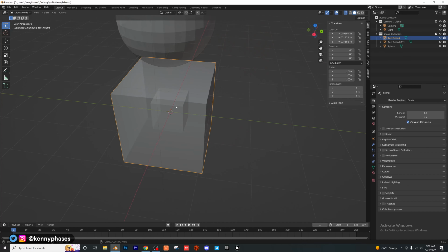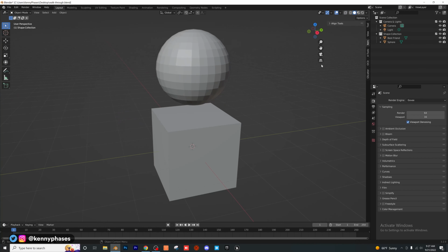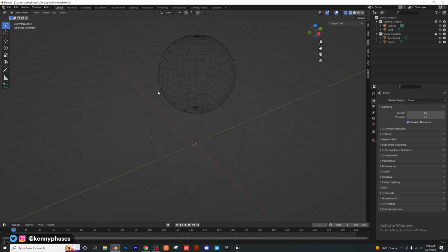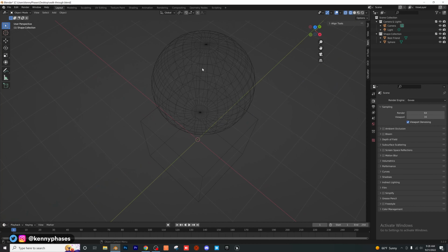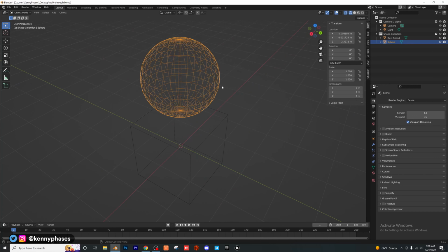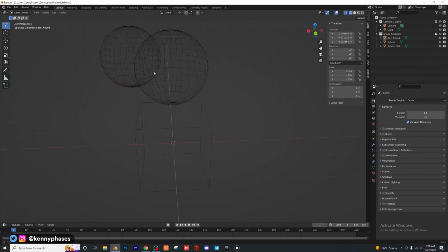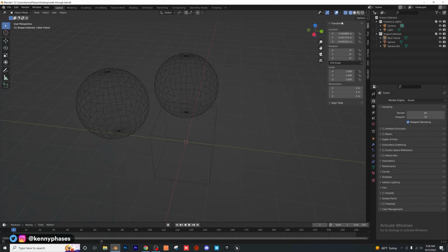I'm going to go ahead and actually delete that inner cube, and I'm going to toggle X-ray back off. Right now we're in solid view, and that is this little sphere right here. This, to the left of it, is wireframe view. And what that allows you to see is the wireframe of the objects, all the vertices, the segments, the vertexes, everything that makes up the object. You'll be able to see it in this view. It is similar to X-ray because you can see through the object, but it just allows you to see the actual geometry of the object and what it looks like. This is super helpful if you want to see if your scene has a lot of complexity to it, or you just want to look at the wireframe view. It's a little bit less taxing. So now let's go back to solid view.